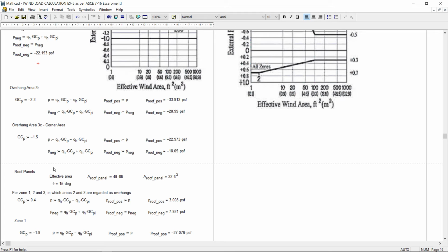So far, what we have done is we have calculated all the possible wind directions, and because of all possible wind directions, we have calculated the wind pressure on every wall, every part of the roof, even the component and cladding. But in our load combinations, the wind load is considered either in one direction or another direction, so in which direction should we consider, and what do we have to do for all these possible calculations?